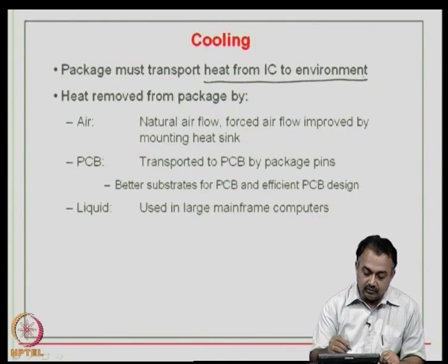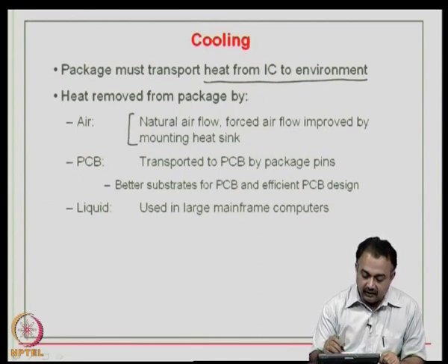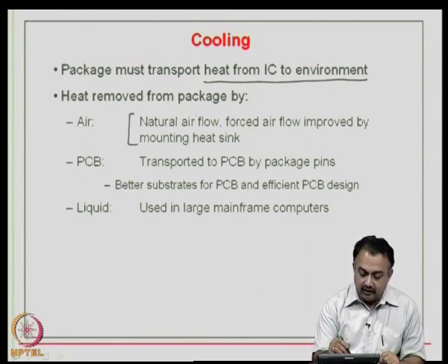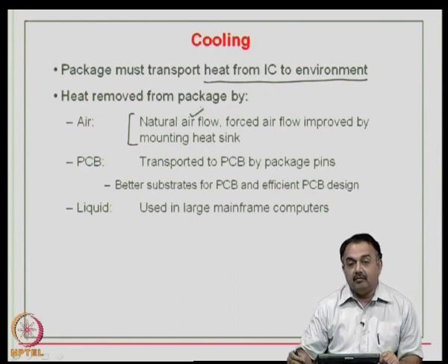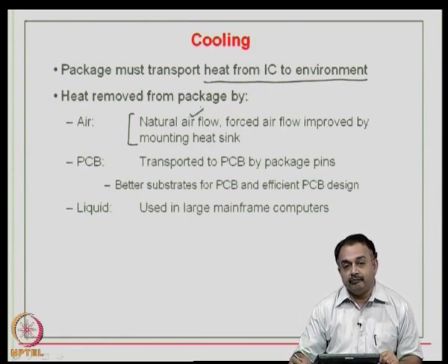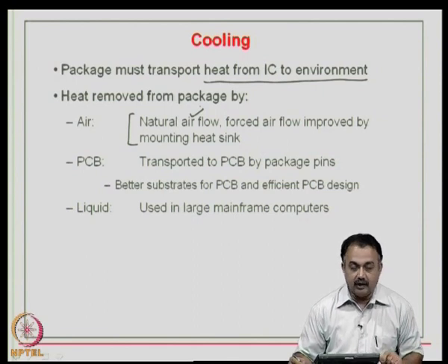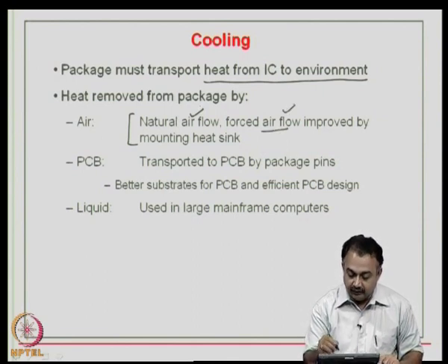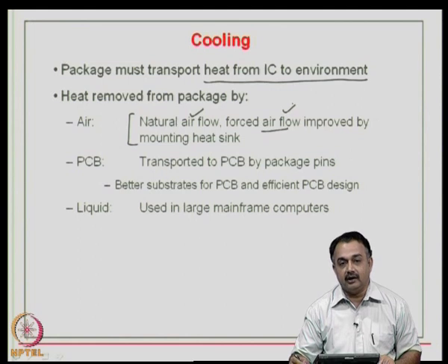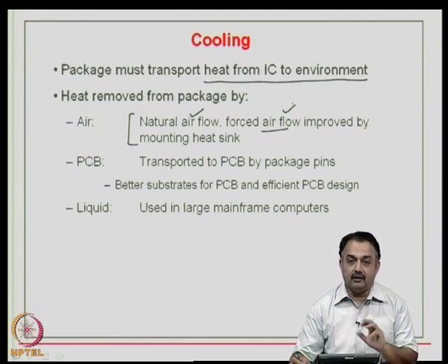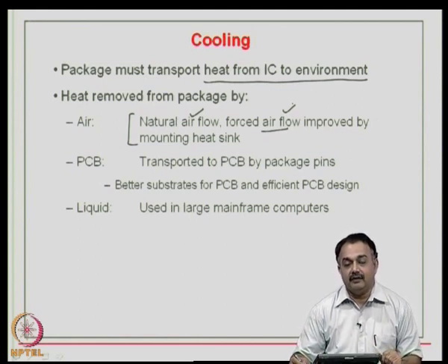So, these are the two common methods that you will see, where either you can depend on natural airflow, but in some cases if the quantum of heat that is dissipated from the active device is large, then you will have to look at forced airflow, and that can be done by mounting a heat sink or using forced cooling by a fan or similar device.